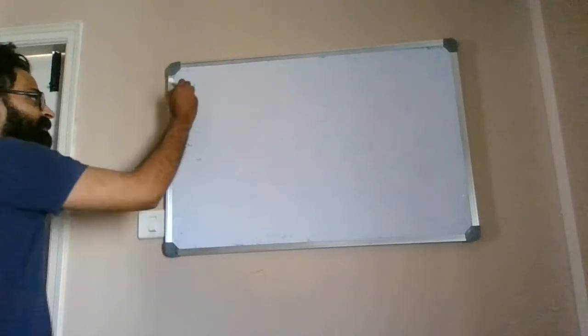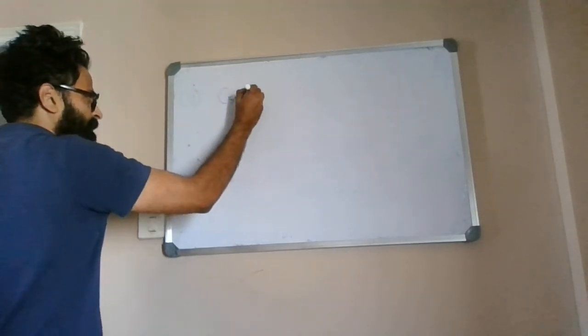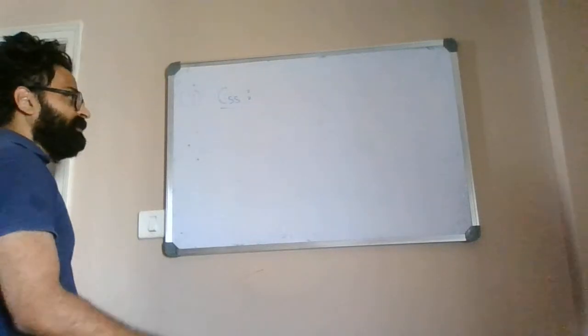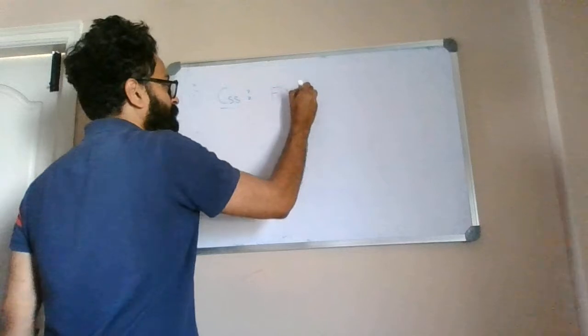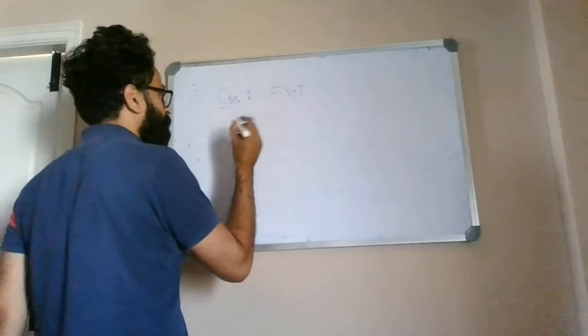Next up, we have the steady state part of the output. So, what is the steady state part of the output? That is what they have asked you, right? To find out the steady state value, you have to apply FVT, final value theorem. So, just to recall, final value theorem.